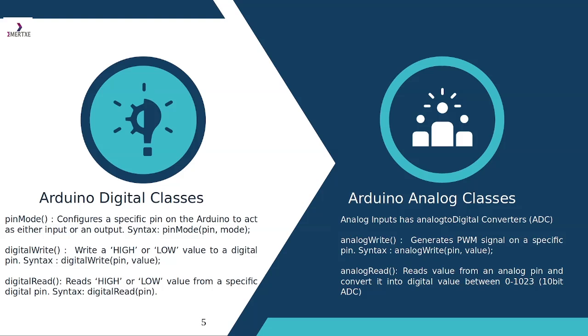And then we talk about declaration of variables. If you declare the pin number as LED1, over here you write LED1 instead of writing the pin number, which is 13. And then we have the digitalWrite. With digitalWrite, it can either be HIGH or LOW.